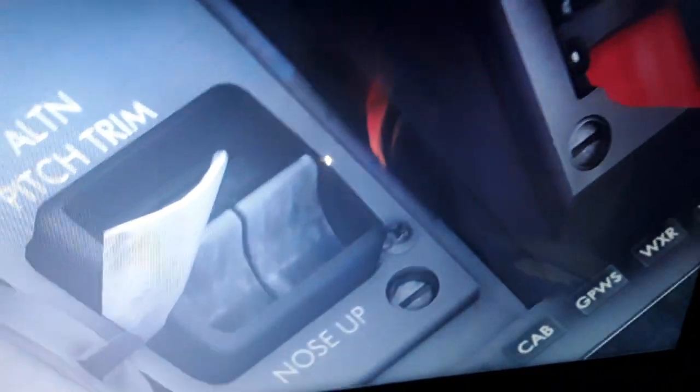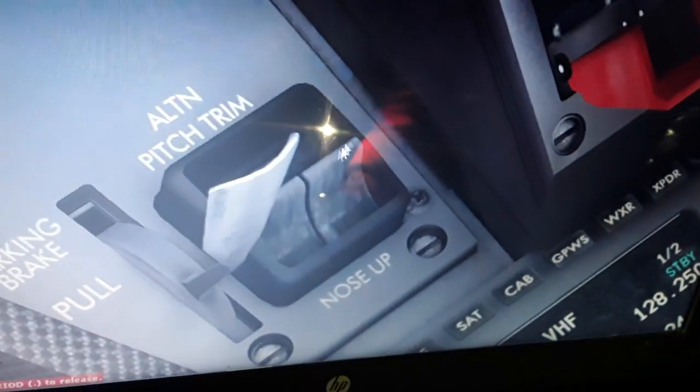So you have the flight control computers. When you fly and move the flight controls over here, you give an order to the flight control computers. So you have the normal, the alternate and direct flow, like in the Airbus aircraft. You have here the alternate flight control computer for the horizontal trim stabilizer, and the auto trim disconnect.